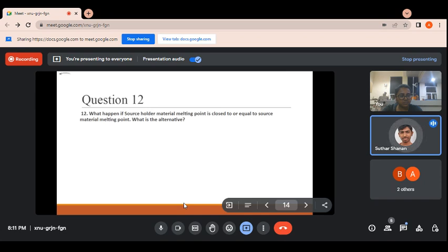Okay. So whether the SU8 process differs upon application, ma'am, because yesterday we attended the problem solving session, and in that session I asked the same regarding SU8. He mentioned that the SU8 procedure, like you have first soft bake and hard bake, and then you have photoresist developer, right? It will differ upon the application.